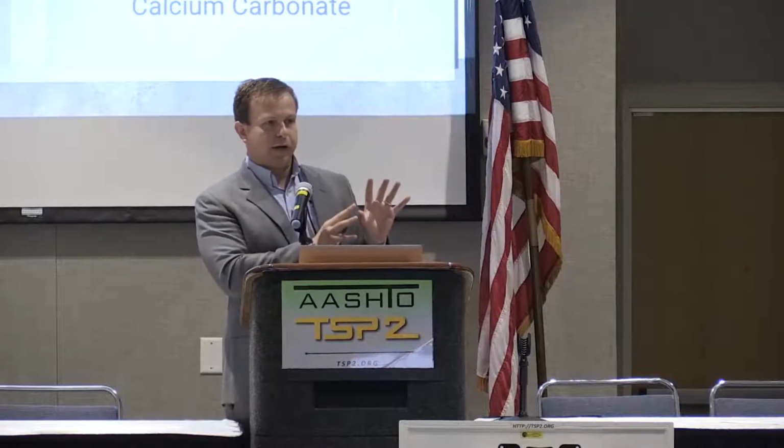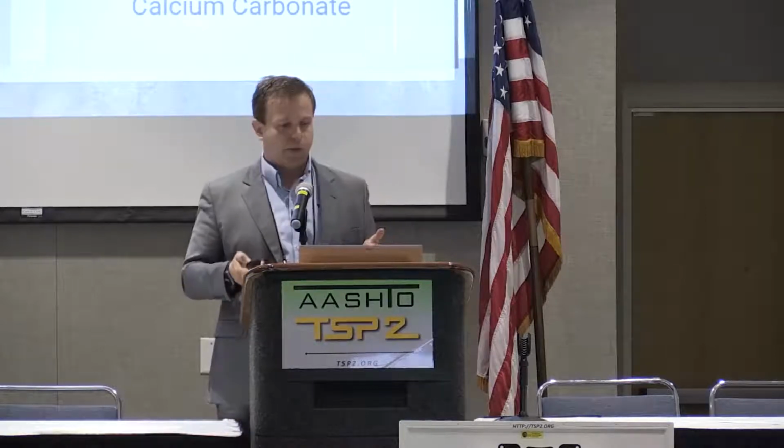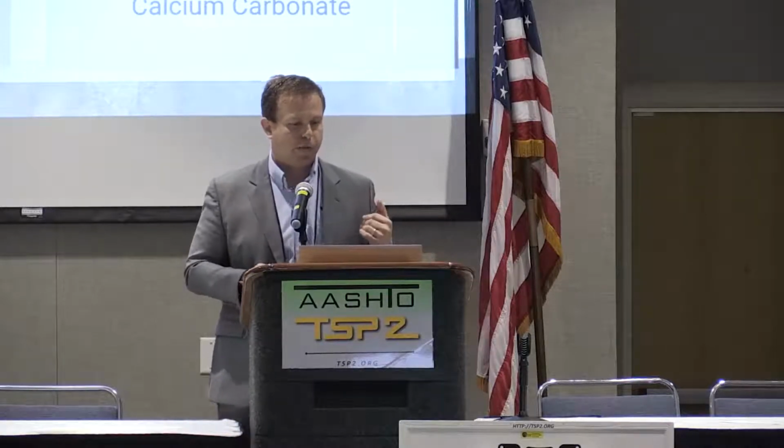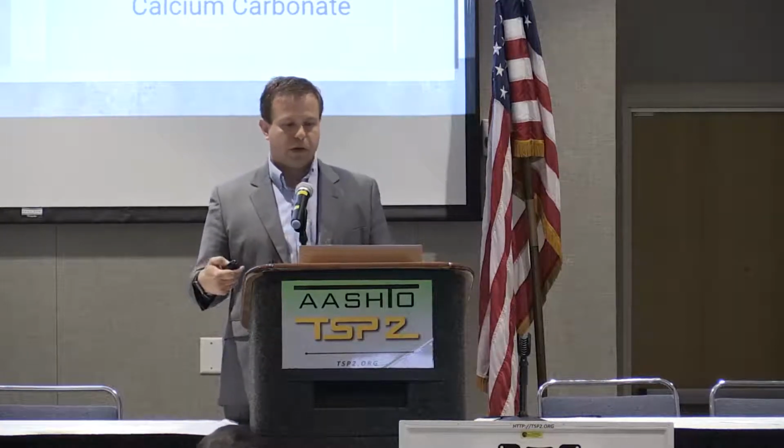You don't have the free calcium, and you don't have new water penetrating. So when we talk about carbonation, we have the formulation here of carbonation, and carbonation is not going to happen because we are removing calcium, the free calcium available, and we are also removing water from that equation. So that's why you're not going to have carbonation.